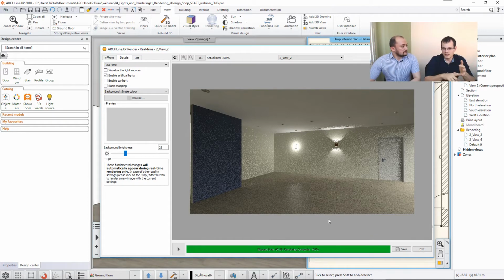Yes. The other thing is that when you're doing rendering, you always have to focus on the larger textures first. In this case, it would be the ceiling, the wall, or the floor. And another thing here is that you should always focus on those things which are in focus. So if there is some kind of central object, maybe a desk or anything, then that's the thing, but you have to figure that out after the large surfaces. So everything else, move to another layer, disable, and then you can work with these larger surfaces.